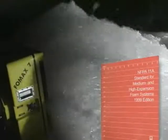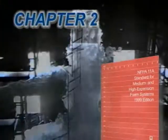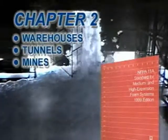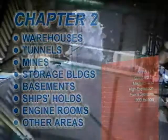In fact, because of their unique capabilities, the National Fire Protection Association established Standard 11A specifically for medium and high-expansion foam systems. NFPA 11A Chapter 2 covers total flooding systems for areas like warehouses, tunnels, mines, storage buildings, basements, ship's holds, engine rooms, and other enclosed areas. The basic concept of total flooding is to fill the space protected to a level above the highest fire hazard.